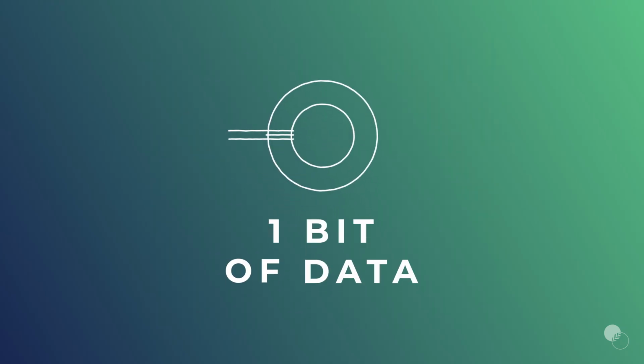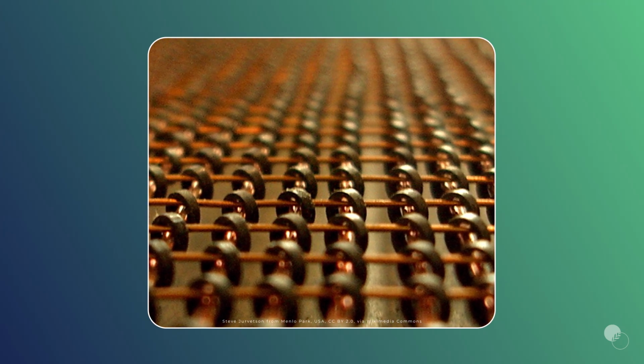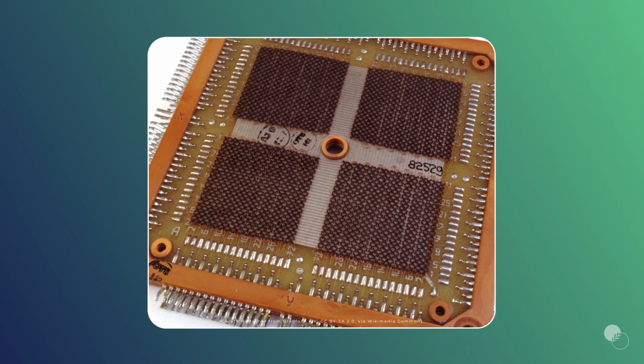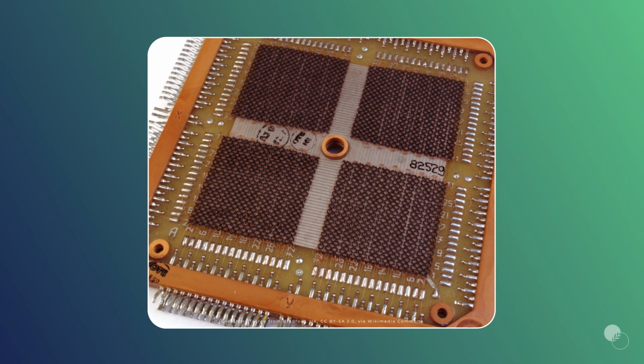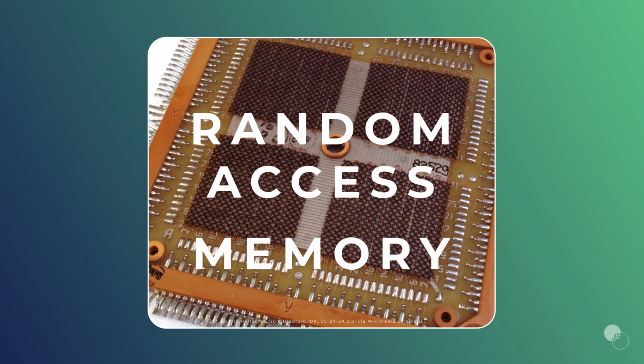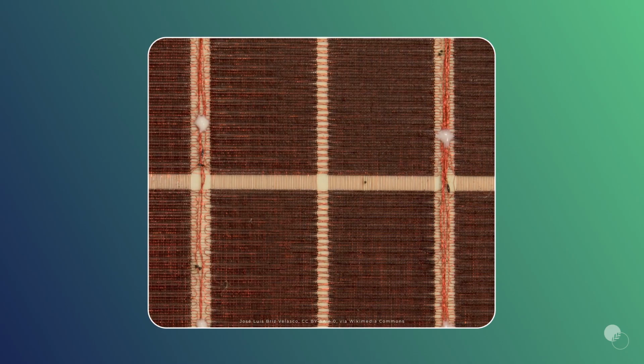Now this ring only represents one bit of data, so in order to store larger amounts of data, these were arranged into grids. This then allowed another huge leap, which was that this was not sequential access like the previous delay line memory. Any bit could be accessed when needed without waiting for a sequence to loop, giving birth to what we call random access memory, a huge necessity in allowing computing to be fast and efficient.